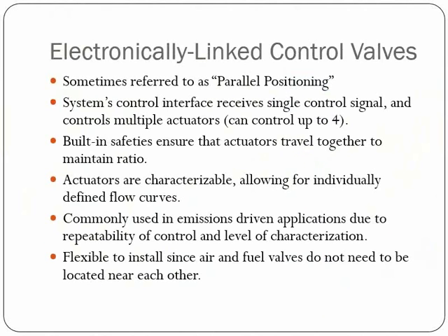We see this type of system commonly used in emissions-driven applications because of the repeatability of control and the amount of characterization. As I had previously touched on, it's important that we maintain very, very tight control for an emissions-driven application because that optimal NOx window is so tight, and these emissions-driven applications have permits associated with them.